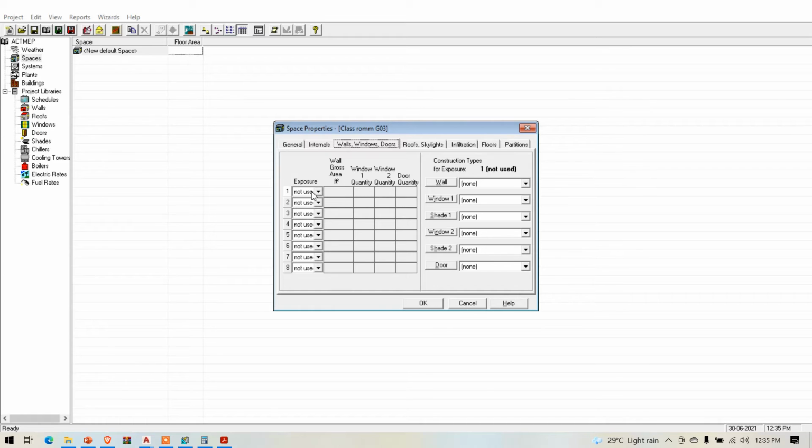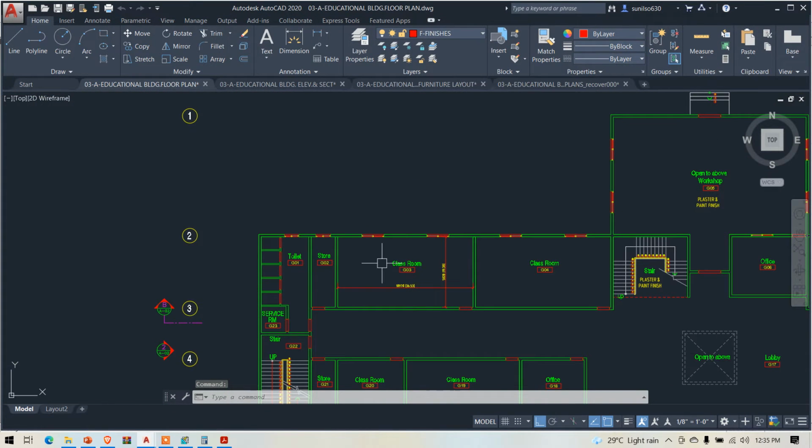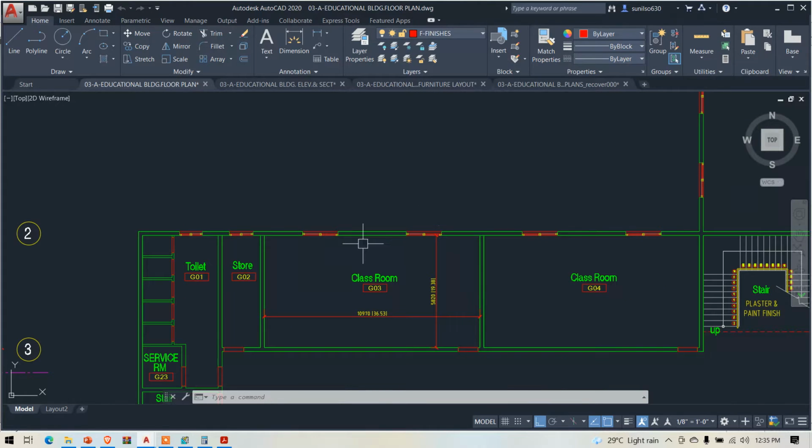Here we are going to consider the wall, especially what they call an exposure wall, which is exposed to sunlight. We discussed last time what a wall is. Here in this room we are going to do the load calculations now. In this room we have only one wall that is exposed to sunlight. The other three are partitions, which are non-exposed to sunlight. So the one exposed to sunlight is what we consider as a wall.